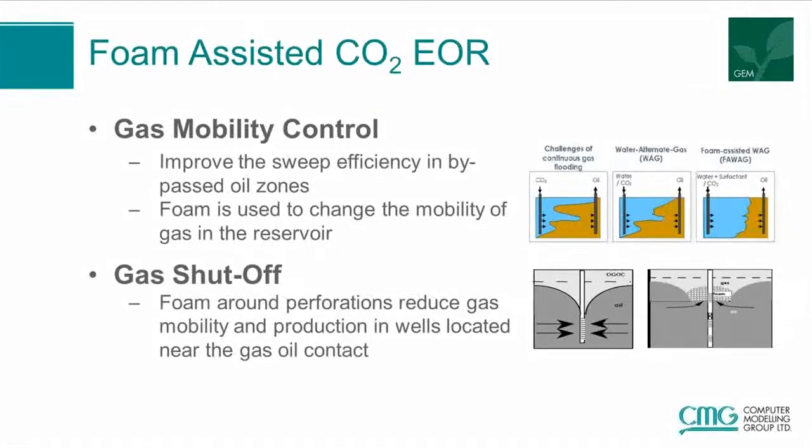In fact, the foam is used to change the mobility of the gas in the reservoir and improve the sweep efficiency. In cases where we have a well drilled near the gas-oil contact, you can apply foam around the perforations to reduce the gas mobility and production in the wells.